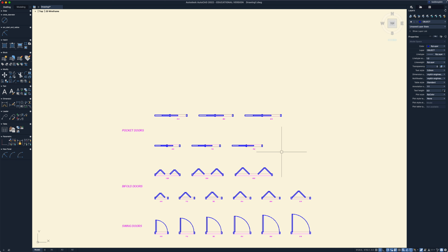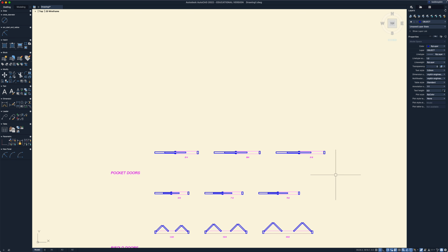Now they're quite easy to draw, very quick. There are 7 of them, but it will not take long at all to get them done. The only thing that's going to be a little bit different is that the garage door is an exterior door. So it's on the outside of the building, and the outside walls of a building are usually thicker than the interior walls because they're structural. They're what we call load-bearing walls. They're going to be holding the weight of the floor above or the roof. So in that case, having a thicker wall is going to allow that wall to fulfill that function.